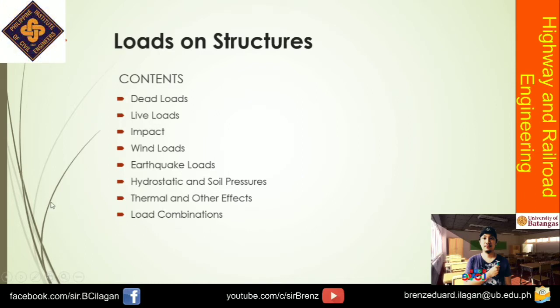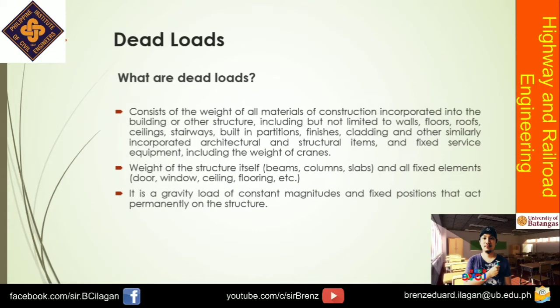Then the load combination, so this will be discussed in your higher year subjects. So to be specific, I think mag-start kayo with reinforced concrete design. So what are dead loads? So isang magandang example niyan is yung mismong weight ng iyong structural member. So kung meron kang concrete, you need to consider the density of the concrete, then multiply it by the volume to get the dead load.